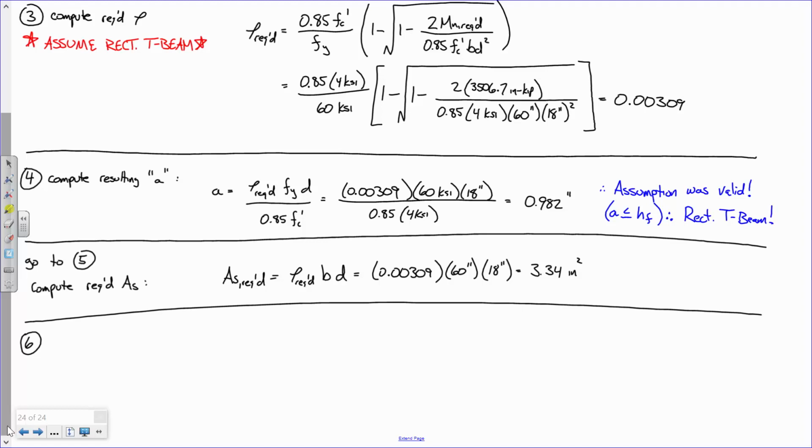It's that simple, okay? What I would do if I were you, just for the heck of it, is go find a reinforcement pattern that works. If you want a little extra practice, and I don't know how appropriate that would be since the number is so small, maybe try to find a pattern that has two layers of reinforcement. The only thing you have to be careful of is your minimum beam width. If you have 2 layers of reinforcement and you pick a pattern that has 12 bars, you evaluate your minimum beam width based off 6 bars, because you only have 6 and 6. Does that make sense? So just be careful on that.